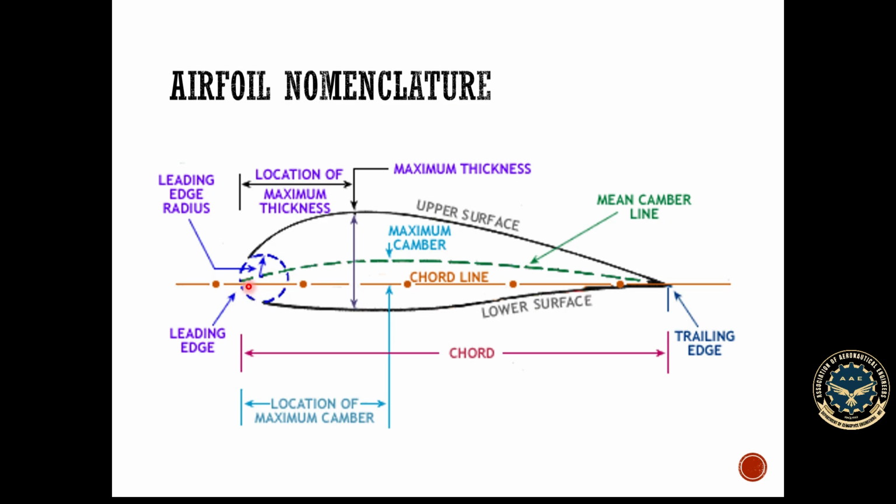A reflex airfoil has a small curvature in the opposite direction at the end, near the trailing edge. So there will be a small deflection of the camber upwards.